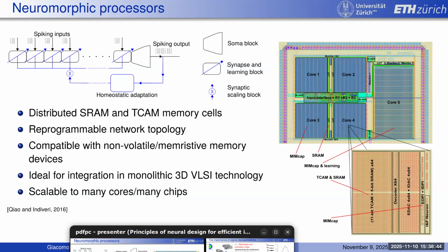However, there is some promise, there is some potential, because these memristive technologies that are being developed, these memristors, are 10 by 10 by 10 nanometers. And they have a long-term memory. Once you change the conductance, you don't need to power them up. So you could replace these 12 transistors per row with one of these 10 by 10 nanometer devices. And so you could really scale things up.